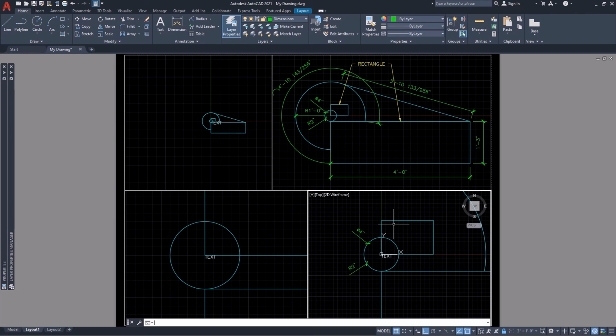In the Annotation panel, pull down the Dimension Styles menu and select Linear Dimension. At the command prompt to select the first extension line, select the upper left-hand corner of the small rectangle, and for the second extension line, choose the upper right corner of the small rectangle, and move your cursor up a short distance and left-click to place the dimension line. Note that this dimension only displays in this 3" equals 1 foot annotation scaled viewport.